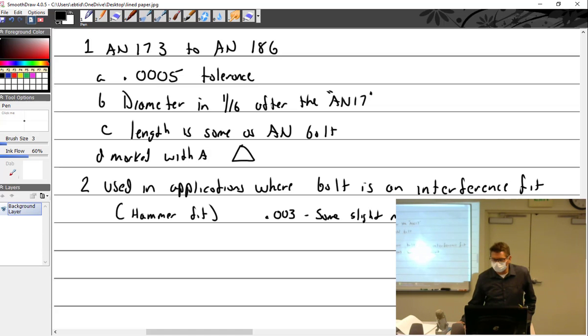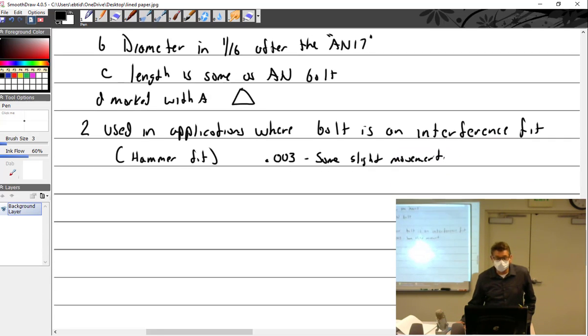So if you put those together and it's a 3/1000 fit loose, and I put it in there, and you can wiggle it, you can just barely perceive a little bit of movement. And 0.002 is going to be no movement, and it's going to be temperature sensitive.